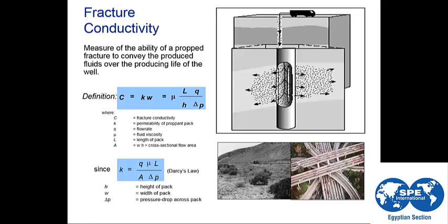We can calculate it from the length of the pack of the proppant and the Q of the pumping flow rate and the height and the differential pressure applied.